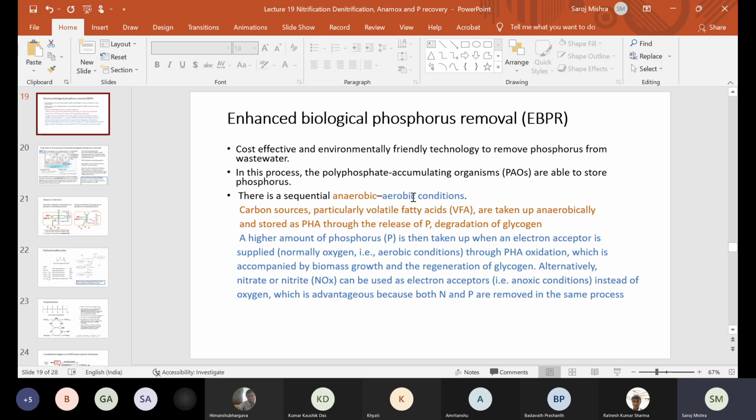In which case, in the wastewater stream, if you are removing nitrate, you are also simultaneously carrying out denitrification, because that nitrate, if used as an electron acceptor, is going to be reduced to molecular nitrogen, and that is nothing but a denitrification event. Are you able to understand? Yes, ma'am, I am able to understand this part.